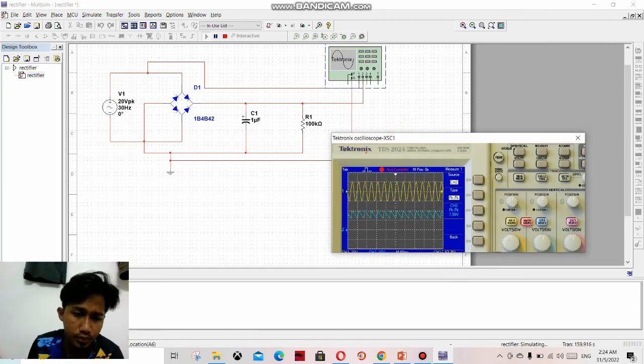So it maintains the voltage across the load resistor until the capacitor recharges once again on the next positive slope of the DC pulse. In other words, the capacitor only has time to discharge briefly before the next DC pulse recharges it back to the peak value.